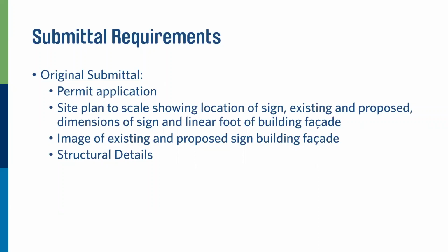Before and after, if you're replacing a sign or something like that, or just your rendering, those work great. All the dimensions on it. We need to see your structural details. That's what I talked about today in the building code. I need to see those details. How is it being attached to the wall? How is that monument sign coming up out of the ground? I have to see those details.